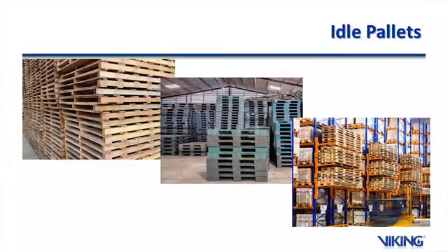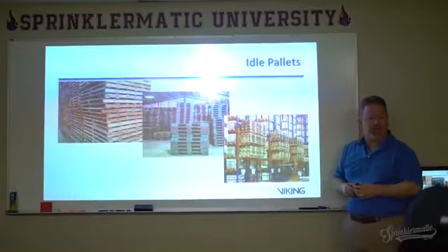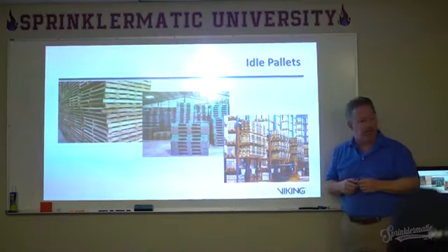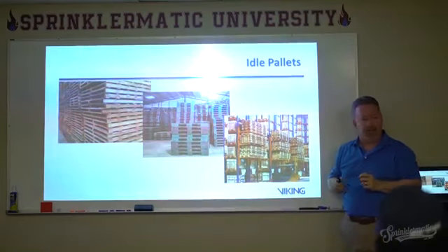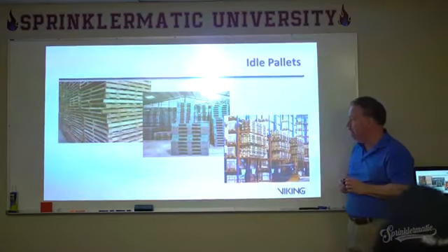Protection of idle pallets. Again, idle pallet, that's a big fire hazard right there, and plastic ones in particular. Okay, best way to protect idle pallets is outside the building. Right? Get them outside. That's the best way to provide that protection.